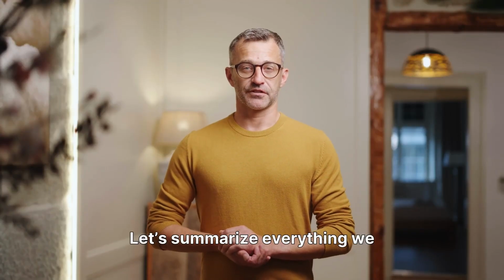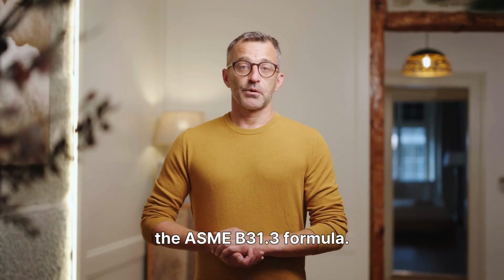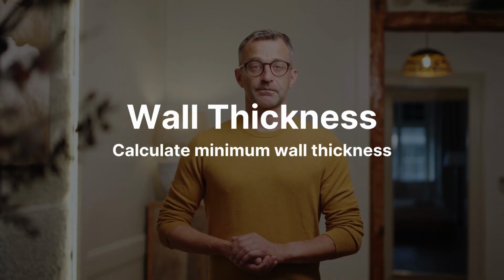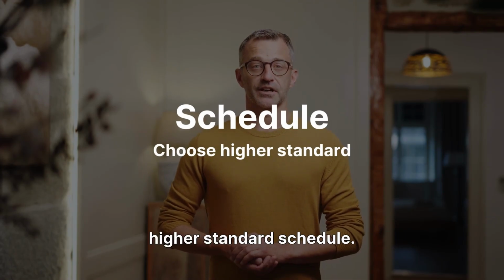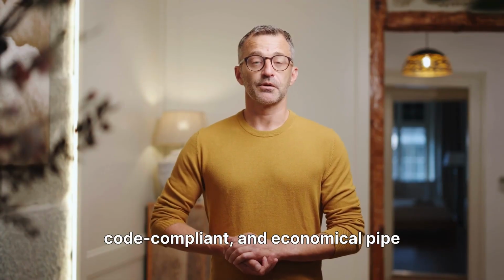Let's summarize everything we learned. One, start with the ASME B31.3 formula. Two, calculate the minimum wall thickness. Three, add corrosion and manufacturing tolerance. Four, choose the next higher standard schedule. And there you have it, a safe, code-compliant, and economical pipe design.